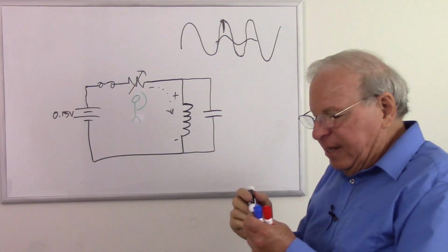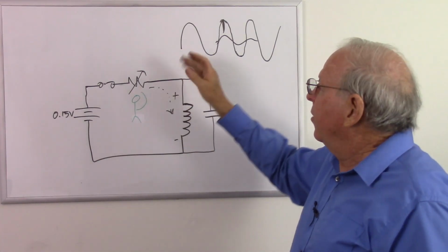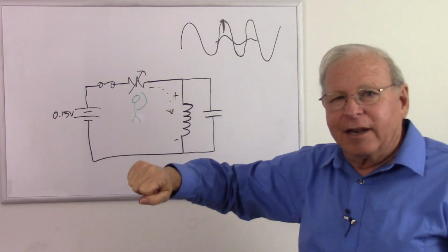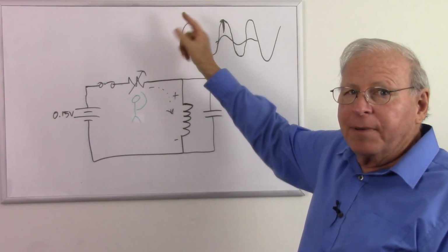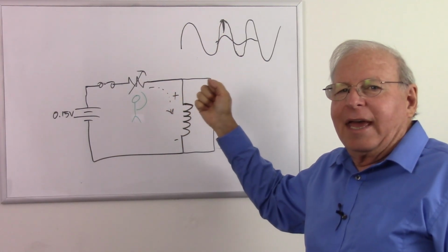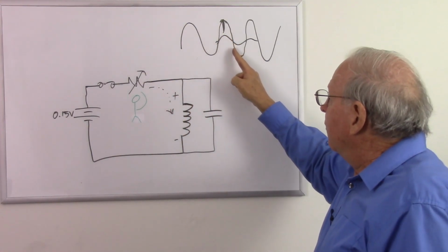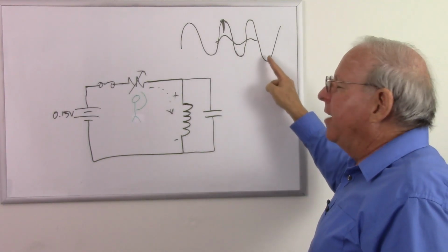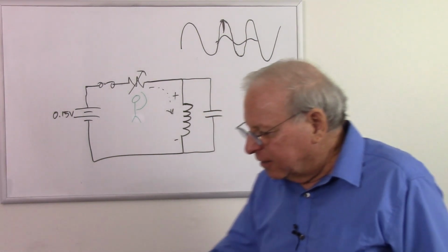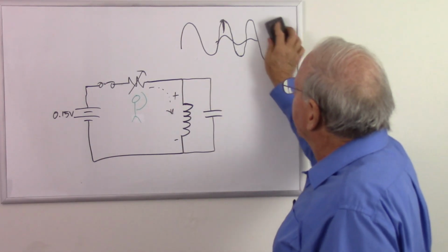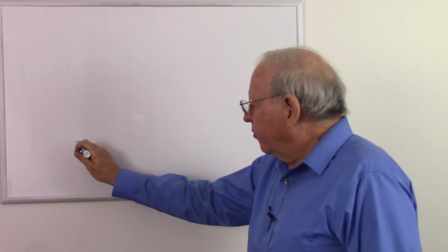And so all we need is something that's going to follow this and decrease the resistance at just the right time to push that voltage up, increase the resistance at just the right time to allow this voltage to go down. And then we have a nice little sine wave oscillator. Now enter in the tunnel diode again. So let's redraw our circuit over here.